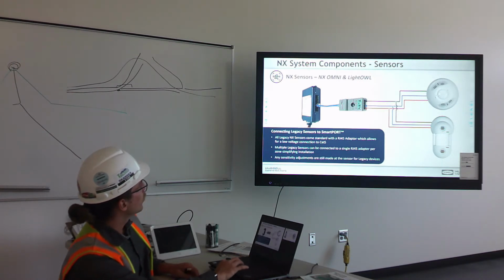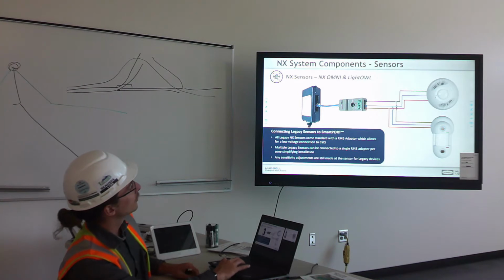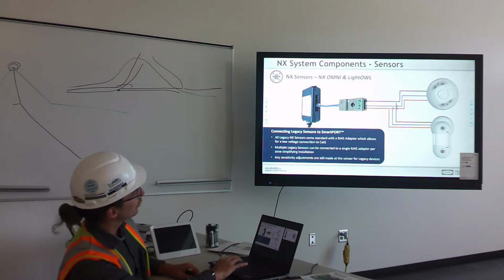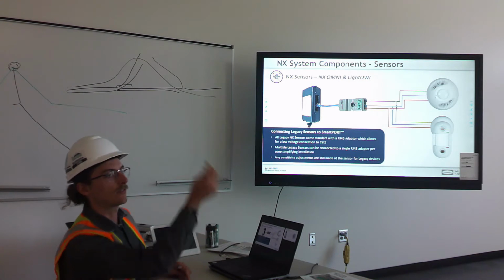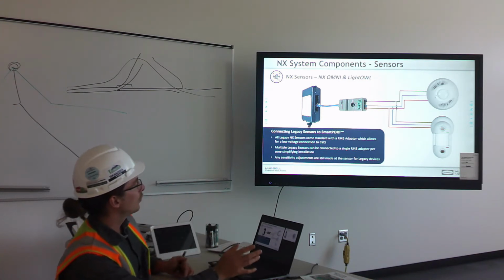This shows what the wiring will look like back to the controller. So you've got just your standard 3 wires: your common or ground, your 24-volt power, and then that actual control signal, which will be going back to your occupancy pin on this terminal block, which then takes Cat5 back to the controller. So a good point to mention here.